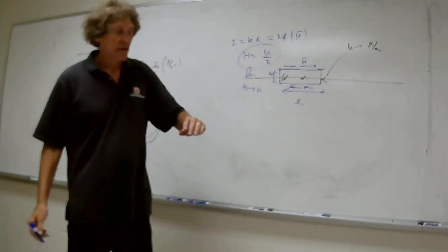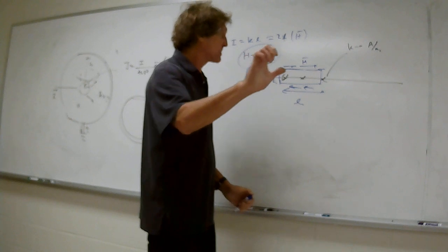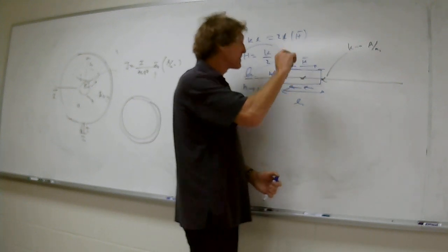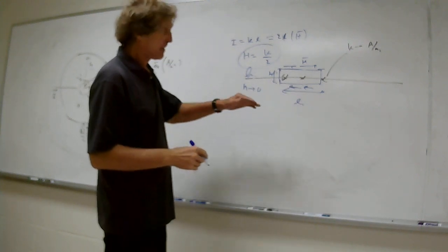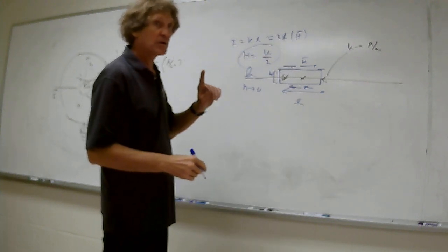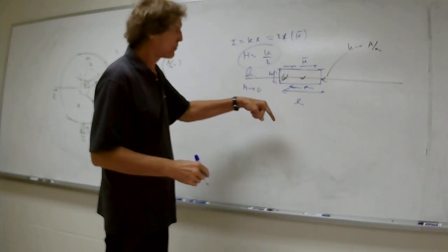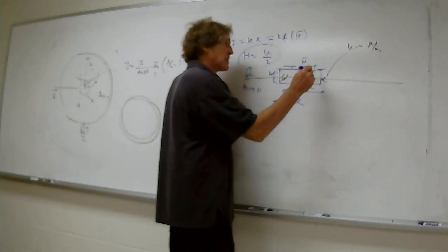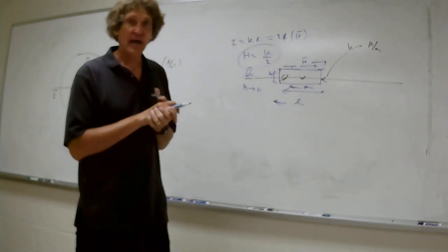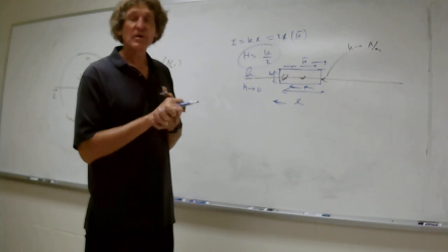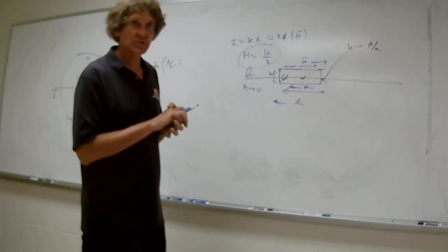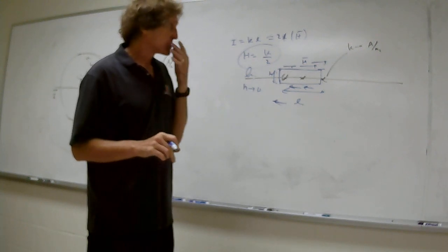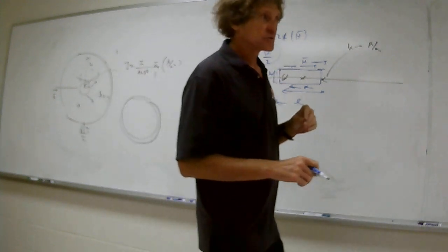All right, this is important. Use your right hand, put your thumb in the direction of the current. Your fingers will curl around the direction of the H field. The H field is not a function of distance away from the plane, simply where it is with respect to the vertical point. If it's below this, the H field will be going this way. If it's above it, it's this way, but the magnitude is K over 2. Y'all follow me? That's a real important thing to know for a thin sheet like that. People often make these problems so complicated, but this is useful information too.